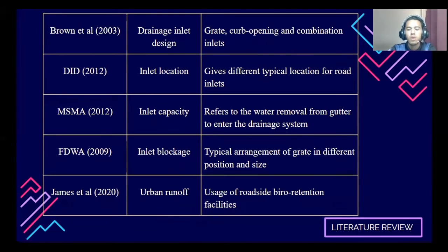And then we can focus on the inlet criteria, which are inlet location, inlet capacity, and also inlet blockage. These criteria can be considered to define how to choose and how to design the inlet drainage facilities.